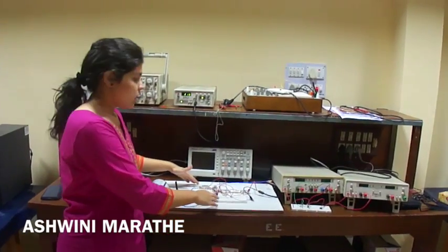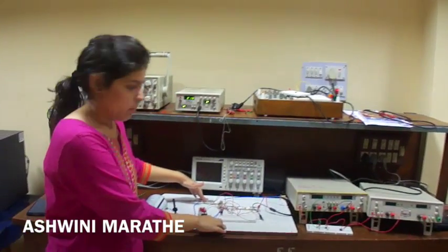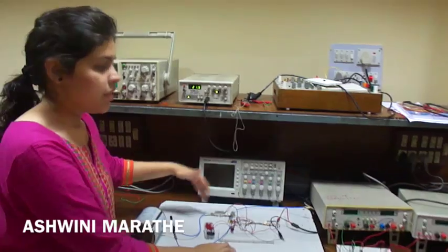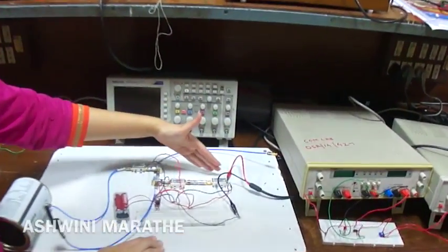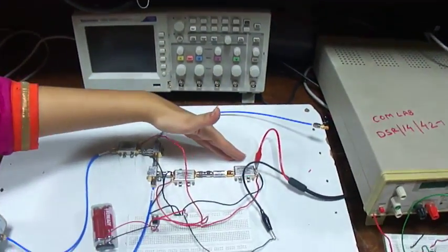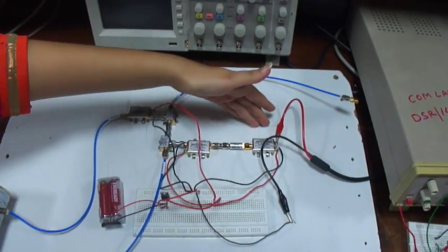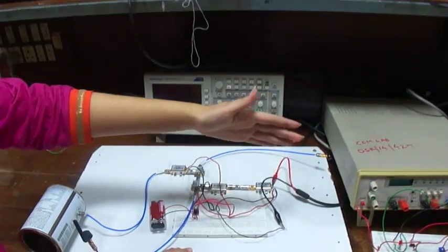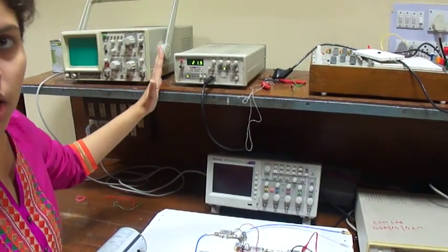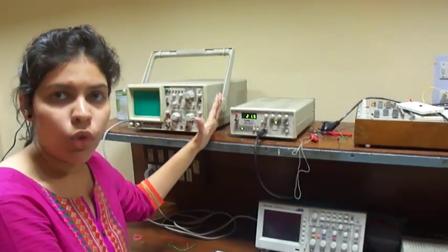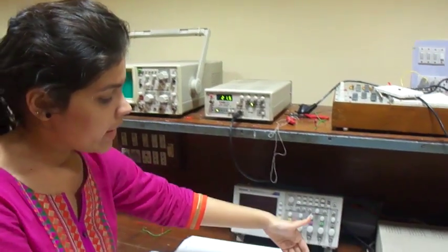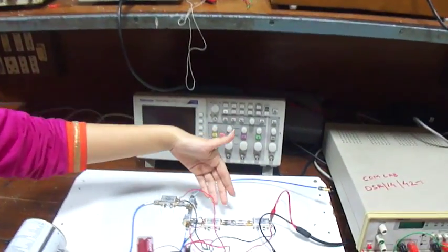This is the actual circuit diagram of what we had seen on the blackboard. Like we had seen, the circuit starts with an oscillator. Here the oscillator generates a signal with 2.4 GHz frequency. Input to this is a modulating signal, which is a triangular signal with frequency 25 Hz and 2.5 volts peak to peak. Next, there is an attenuator and a power amplifier.